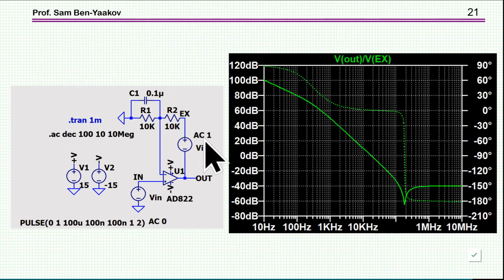Okay, there is an injector which is put like here, or usually it will be a small resistor on which we impose a voltage, which is like a voltage source, and this is what we do. So if I do that, here is what I got. You see, this is the loop gain, this is the phase, and here at 0 dB, I see 0 phase.